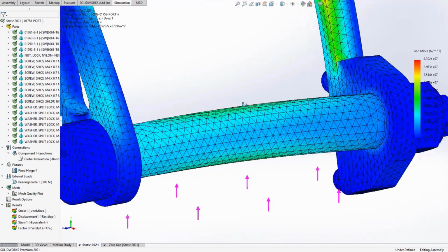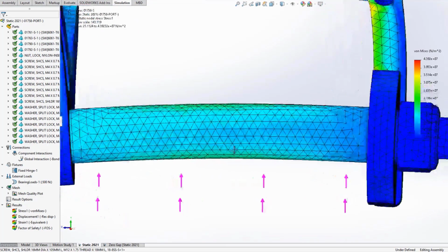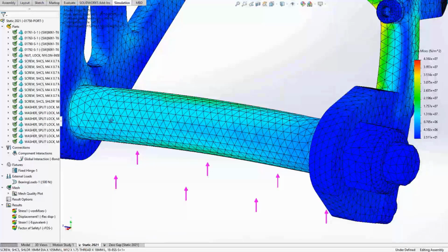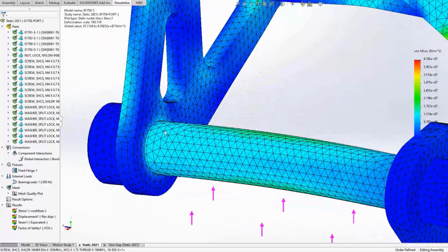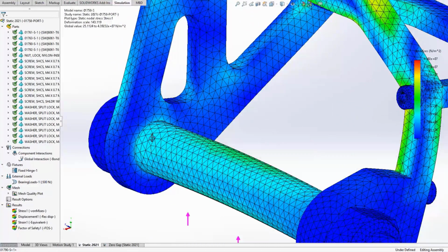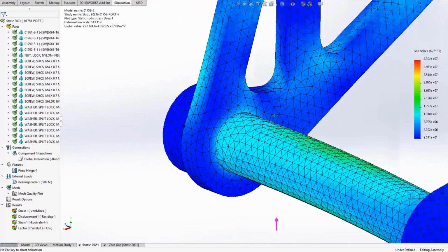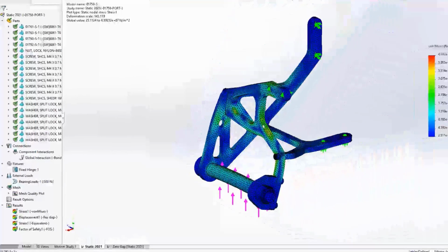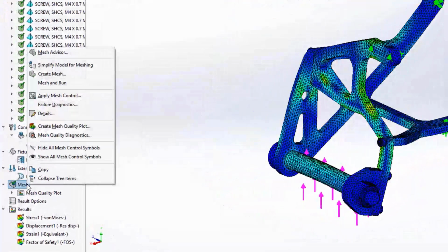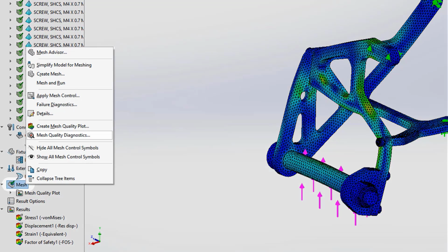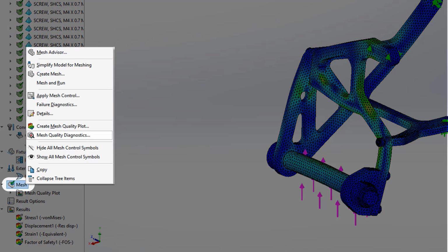Now, another enhancement for Simulation 2021 is the addition of correction factors when it comes to cylindrical, spherical and conical faces within there. There's also been some enhancements to meshes where they don't have common nodes within there or incompatible meshing for any of our simulation whizzes out there.